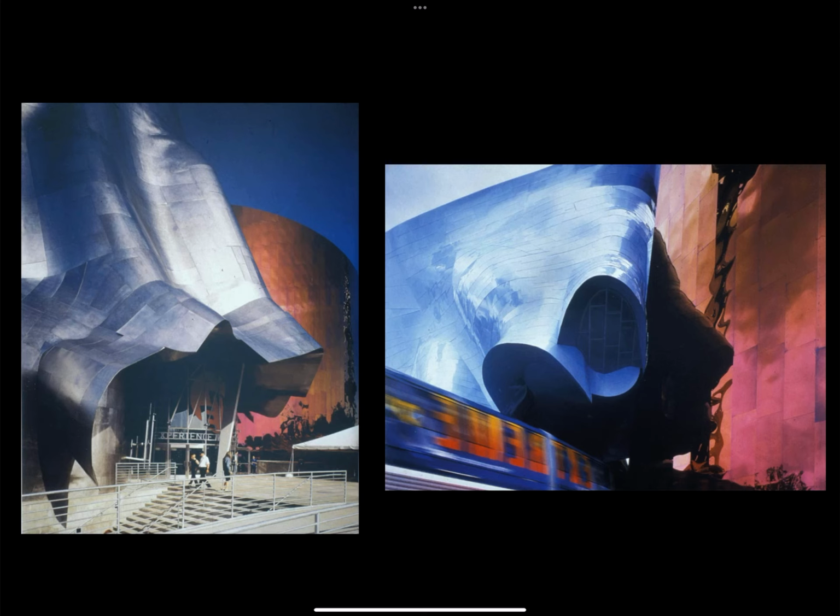It doesn't like most other materials, and so it has to be isolated from other metals like steel, copper, or lead. It has to be isolated from preservative treated wood. It has to be isolated from concrete. And this isolation is usually a coat of tar-based paint, or it could be a thin layer of neoprene, which is rubber.